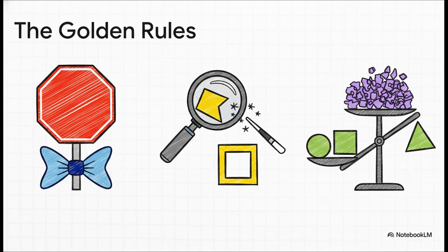And finally, rule number 3, and this is so important, always choose quality over quantity. A coarser mesh with beautiful, well-shaped elements will almost always give you a better, more accurate, and faster solution than a superfine mesh that's filled with junk. At the end of the day, it's not about having more elements, it's about having the right elements.